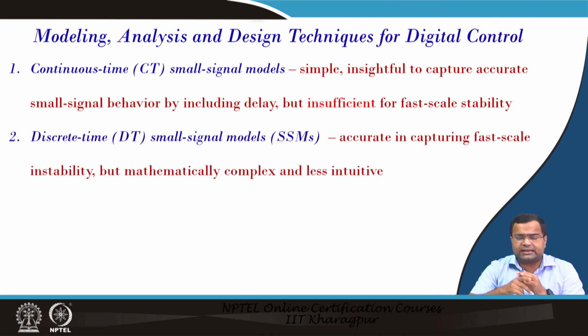Then we learned discrete time small signal modeling, which is very accurate. It can capture all sorts of instability, but these methods are mathematically complex because you have a lot of matrix exponentials and all, and these are less intuitive in terms of pole zero.